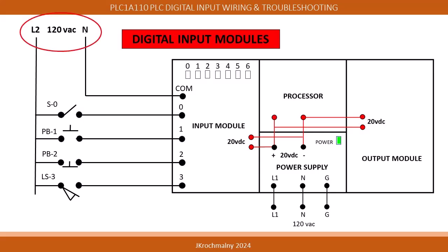As the graphic shows, an applied power of 120 volts AC is available to digital field devices and identified at the top left of the graphic. Other specific PLC input modules can accept other applied voltages such as 24 volts AC, 24 volts DC, 12 volts DC, and others. Notice that when associated switches are in the closed condition, this same voltage then appears at the PLC input terminals.